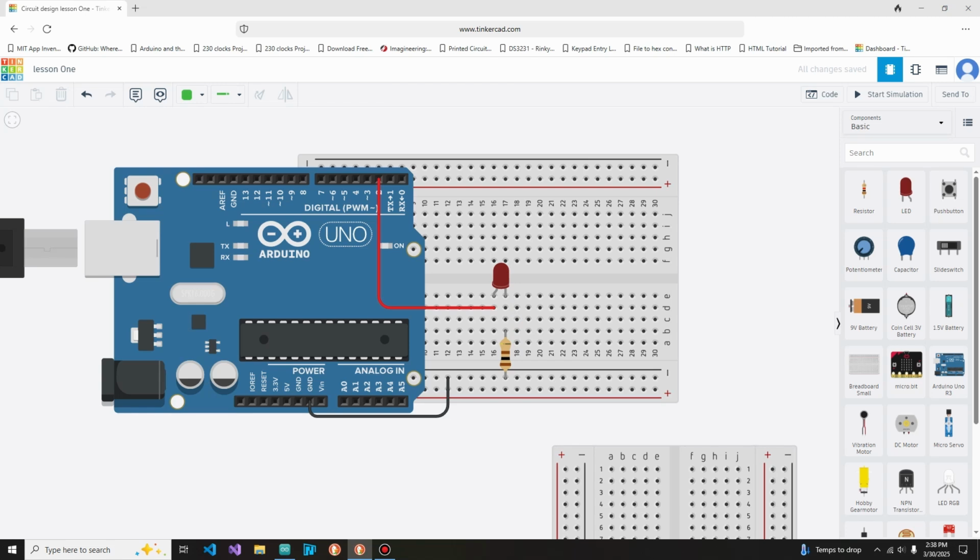Once I get the Arduino, I've got a camera set up here so we can actually see my setup. I'll show you the LED that I'll be using, and I'll show you how to identify these. On here, it's relatively simple because it tells you anode and cathode, but this LED has a flat side to it. All LEDs have a flat side. That will signify the negative or cathode side. And if the legs have not been cut, it will be the shorter of the two legs. If it's a positive or an anode, it will be the longer of the two legs. So they give you two different ways to identify them. If the legs have been cut, just look for the flat side of the LED.